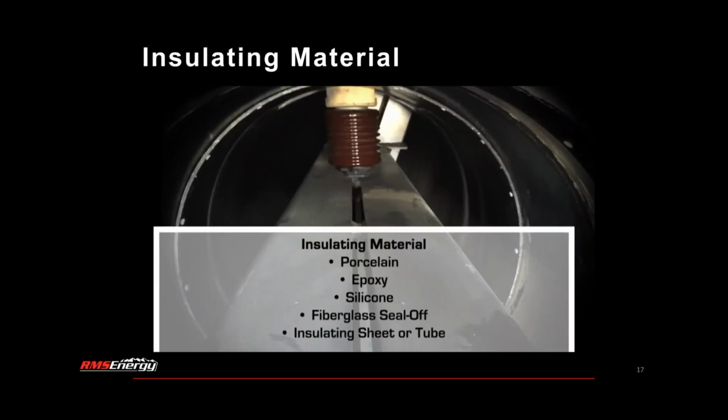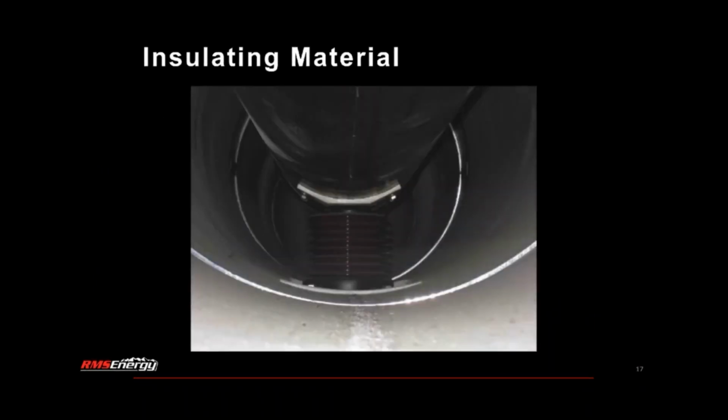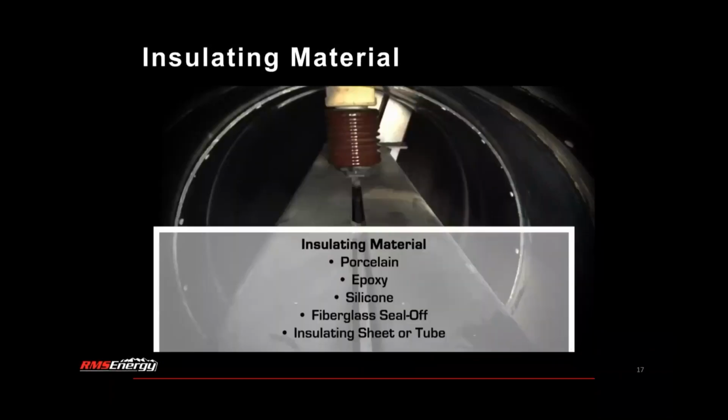We'll also talk about maintaining insulating materials in your insulation system within the bus duct. This is an image of a standoff type insulator commonly found in isolated phase bus. These can be made of epoxy or porcelain, but there are a number of other insulating materials found within non-seg bus and isolated phase bus. You can have fiberglass sheets and tubing for bracing and barriers, as well as epoxy or porcelain seal-off bushings that need to be maintained as well.